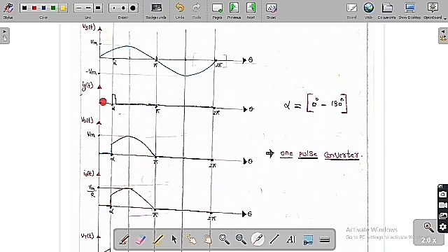We can turn it on in the region of 0 to pi only, only in the positive cycle, but not in the negative cycle. In the negative cycle it becomes reverse biased, so we cannot turn it on. We can turn it on only when VAK is positive and IG is positive, otherwise we are not going to turn it on.